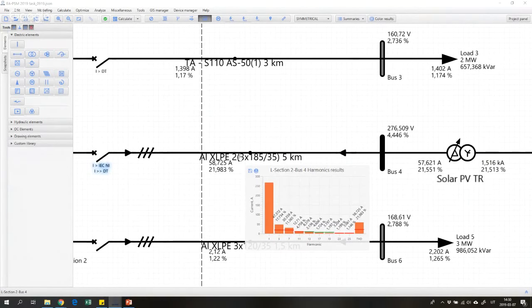If I put my mouse cursor on the cable, the software will show me a histogram of several harmonics. I can see that some of the harmonics have red horizontal lines with them, and some of them have green horizontal lines. The difference between these two is actually limits, again specified by international standards. If we have a red line, like the 5th, 7th, 11th harmonic, it shows that these particular harmonics are exceeding the permissible limit by international standard.